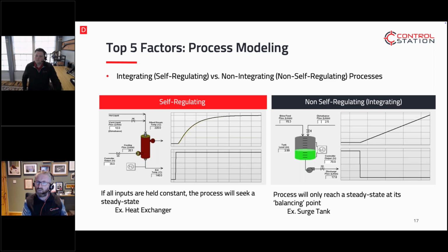What is this tank used for? Why has this tank been put here? Most times they're buffers. We actually don't really care whether it's 50% or 55%, but there has been a habit to tune level controllers the same way we tune temperature controllers. But level control should have a nice float in it, respond and react, and don't flood the bund, but just maintain the buffer. Some designer put the tank there as a buffer system. So we go to the next slide.